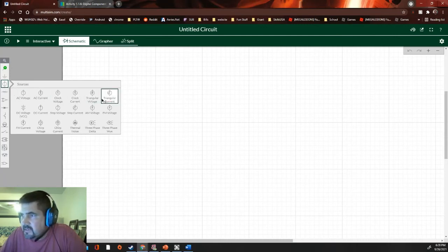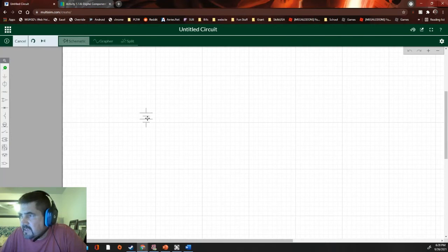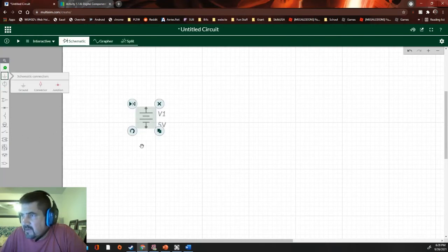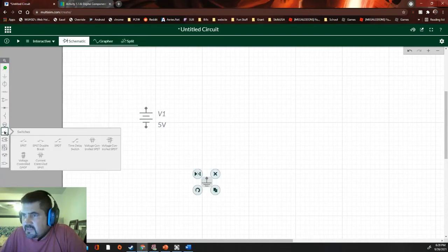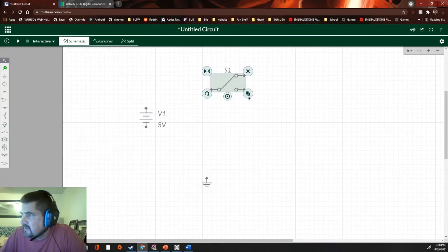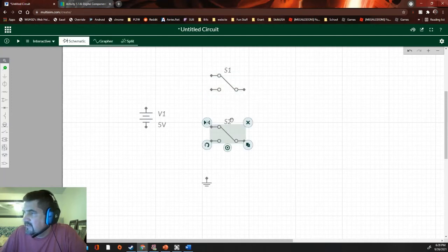We're going to do DC voltage right here. And then of course I'm going to need that ground. So let me click that right here. And I got that. Then I need my switches. So let's click here. We need the SPDT, single pole double throw. And we're going to need 2 of them. So I'm going to flip it with this little inversion button, flip it. Then I'm going to click this copy button right here. And there we go. So I have my 2 switches.